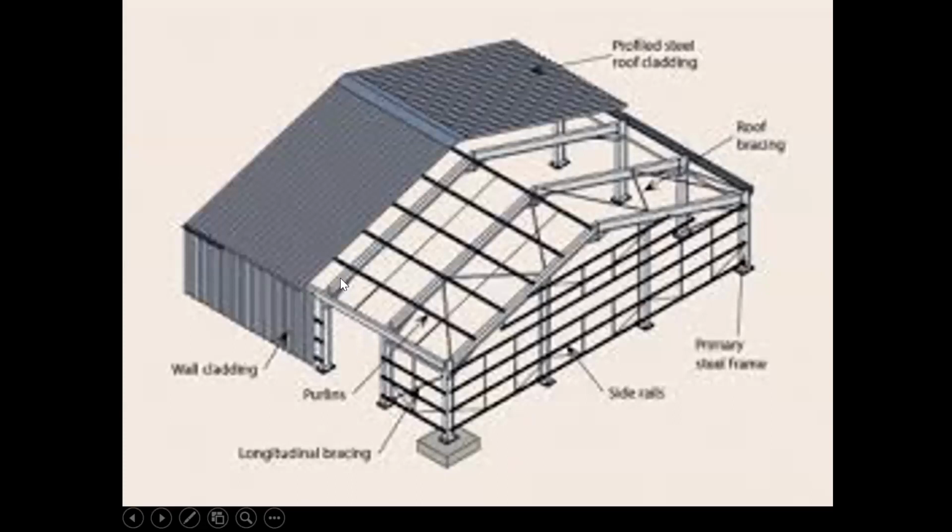Like here is one of the portal frames here. Here's another portal frame. These are the purlins spanning between the portal frames. And then the roofing goes on top of the purlins. So it's a pretty straightforward system, but I must say it's not very highly favored by architects. I've never seen an award-winning work of architecture using pitched portal frames.